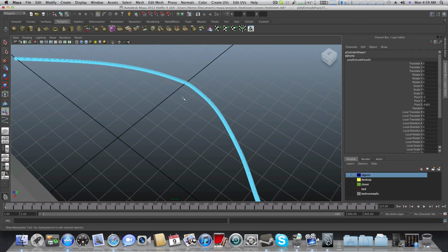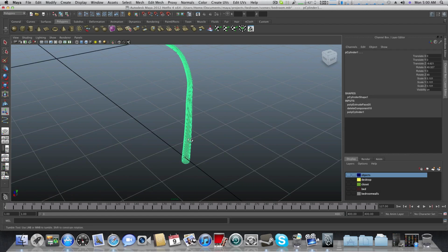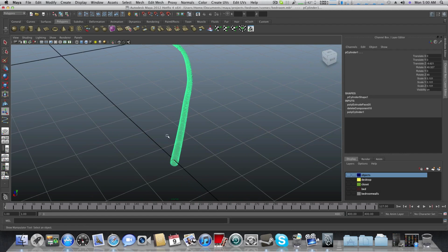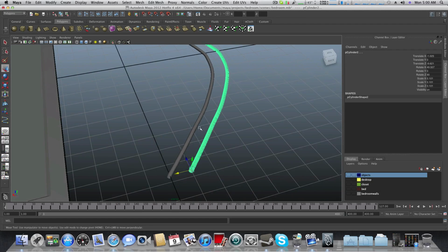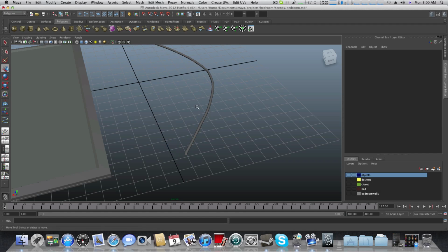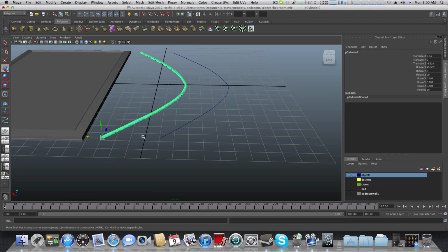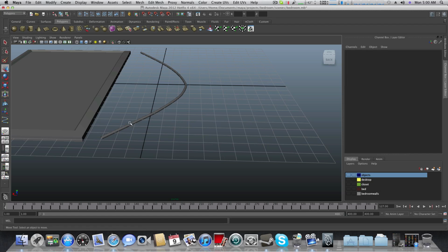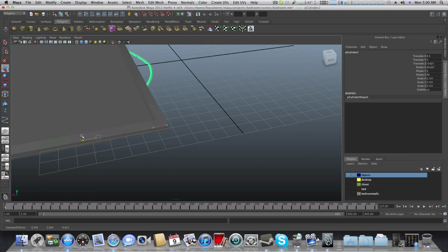Okay, as you can see, it's still in manipulating mode, so tap on F8 to bring it back to green wireframes, and I suggest you also copy it, so Control D and copy it, because in the same case as like the vase, these two have the ability to be manipulated by the curve itself, so we don't want them. We want one piece that it's okay, just move it. Oh, I also duplicate the other one, so that's okay like this.